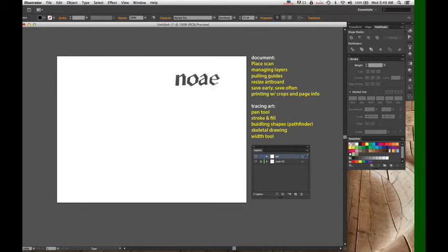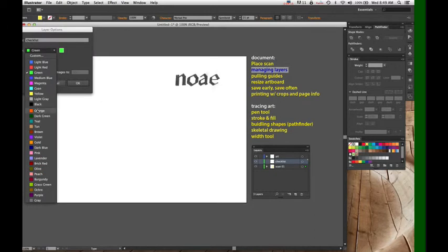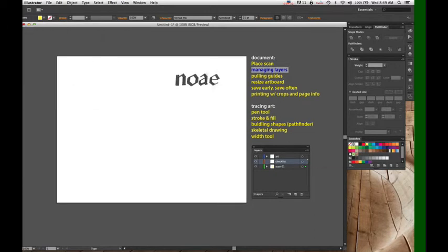And you'll notice now I can't interact with my checklist because my checklist is on the scan layer. So what I'm going to do is create another layer. I'm going to call that checklist. And you can see that when I have this piece of text selected in my layers palette, I have this little green dot next to the scan 01 layer that shows me which layer what I have selected is on. And you can also see the selection outline is green to match the color of that layer. Well, I can just grab this, move it up to the checklist layer. There it goes. Now I can lock my scan layer again, and I can interact with my checklist.